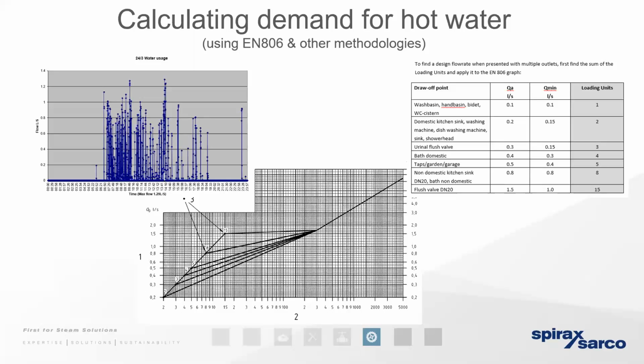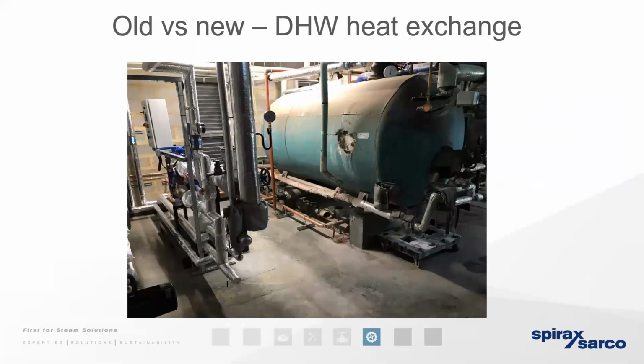Now, as far as those older storage heat exchangers are concerned, they're going to bring our clients a number of different operating challenges. For one, we're holding that hot water in storage. And because the heat exchanger is likely to be oversized, it could well be that the process has changed over a number of years, or it could simply be that it was oversized at the design stage.